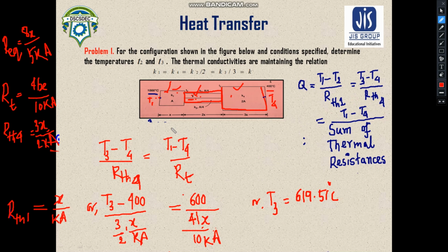So the basic concept to solve this problem lies here. You need to understand that the same heat is flowing through the different walls, and this can be represented via the temperature changes. And this was arranged in a parallel way, so you need to convert it to the series format, and only after that can you calculate the resistances which are in series and just add them up.